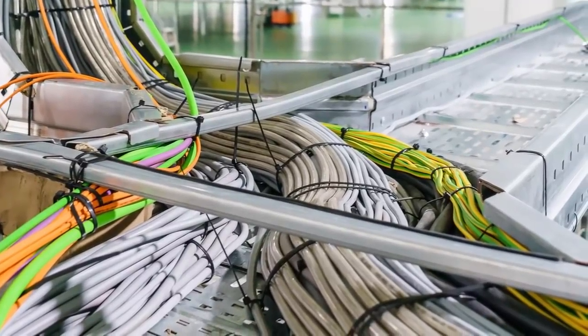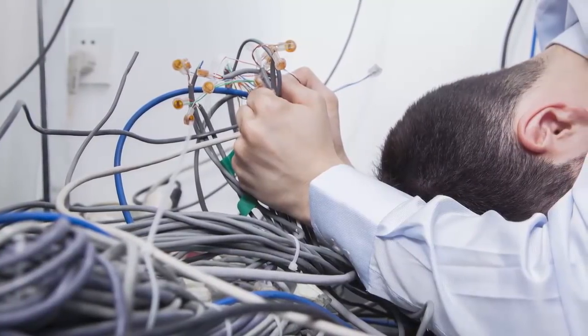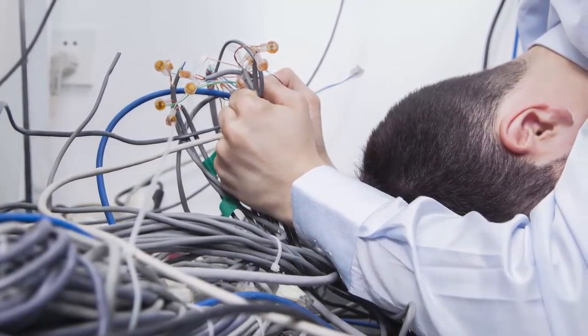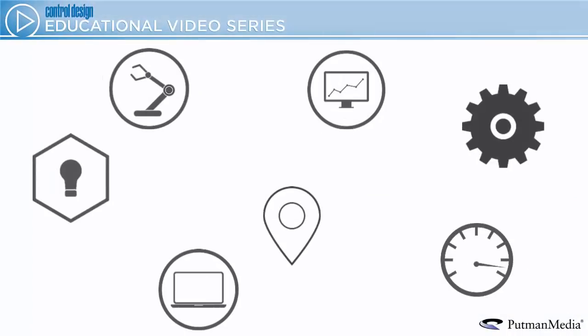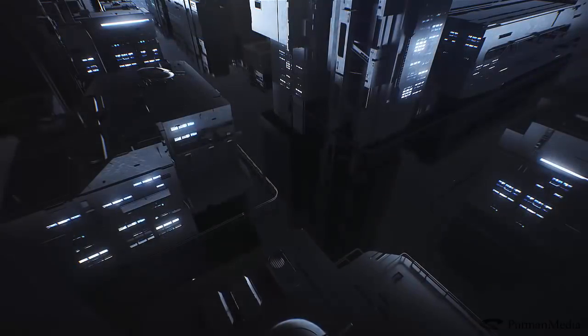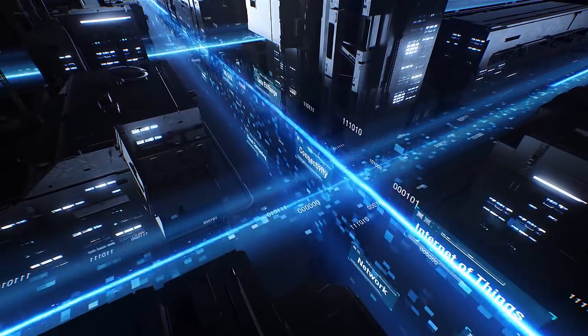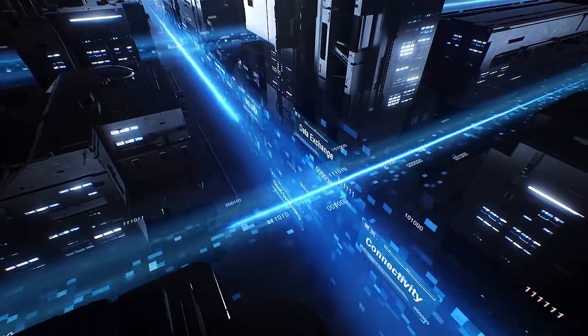Because of point-to-point networking costs and complexity, not to mention the sheer volume of wire it consumes, developers sought to have cables that can gather signals from more than one device at a time. This can be done by sending low-power impulses superimposed on a 4 to 20 milliamp continuous analog signal, or by using digital methods that slice data into tiny pieces delivered in a series. Either way, these analog and digital communications eventually progressed enough that multiple signals could travel over one, two, or several wires, much like the conversations that moved between telephones.